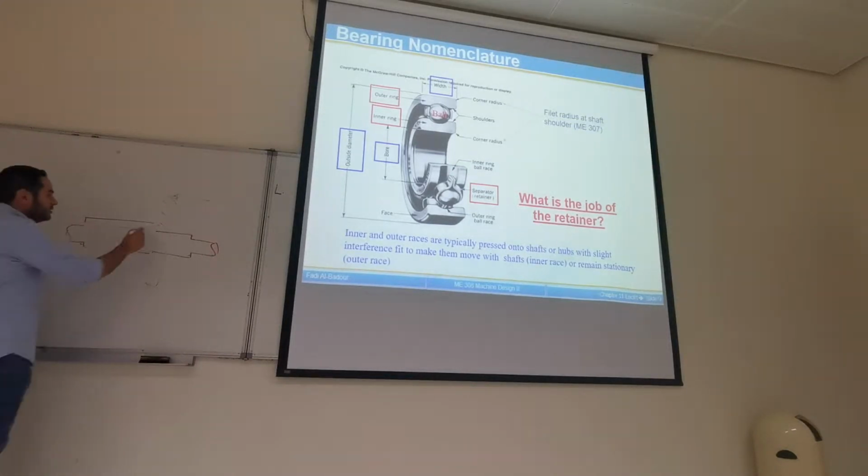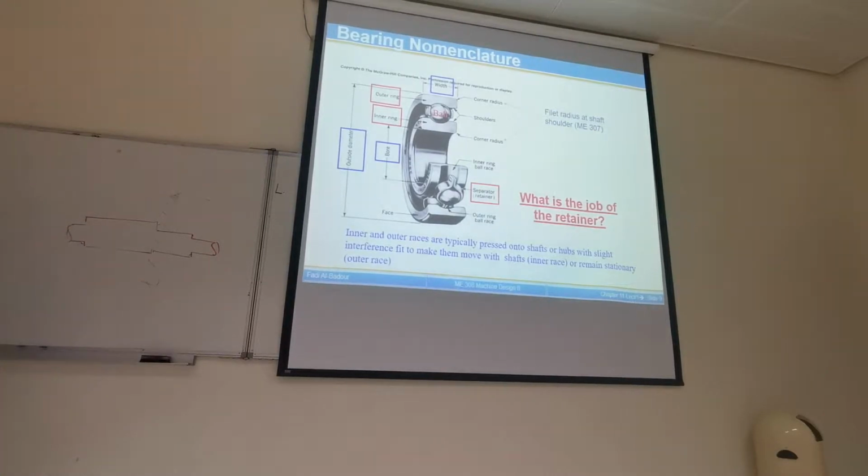So what holds the gear in position? The shoulders. Now the load will transfer to the shoulder, from the gear to the shaft. What holds the shaft is the bearing, so you need another shoulder to transfer the loads from the shaft to the bearings.